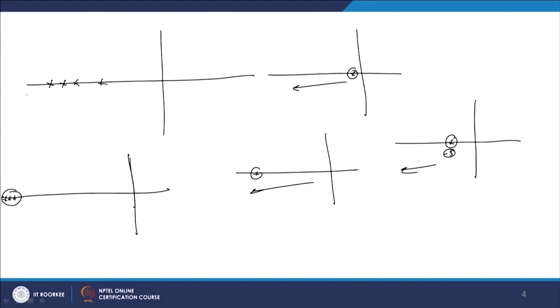That means you have to move the poles to the left side when there is a requirement. If you want to reduce some control energy, let us say there is one pole on the right hand side at 2, you can shift it to say -2. If you move the original system pole from 2 to -2, we require very less control energy. So, that is a thumb rule we can also use.